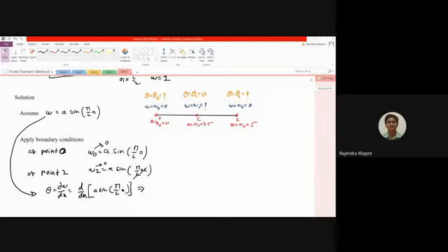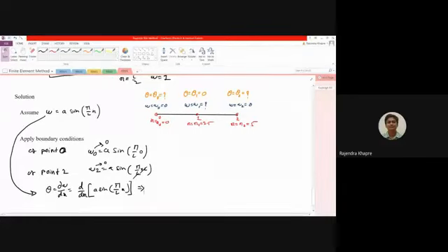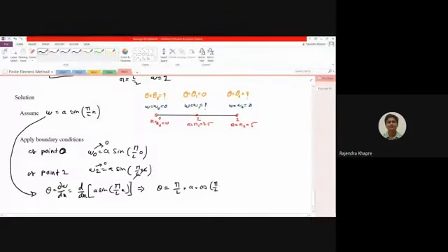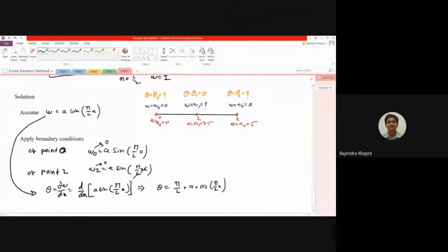Okay, so let me explain. While going for a derivative, you just have to refer to your 12th standard notes, the equations which you have studied earlier. So this theta value, if you go for a derivative, will be something like pi by L. Okay, so x will be gone, then it will be multiplied by a into the derivative of sine, which is cos. So this will become a cos of pi by L into x. So this is the value of theta, that is the rotation equation.